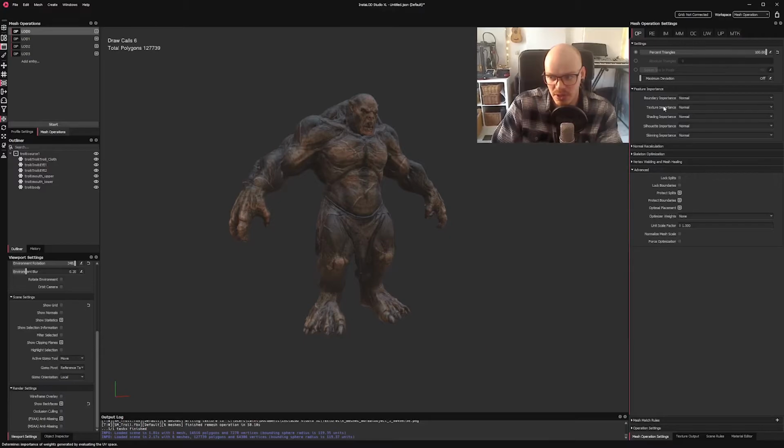That is only really the case when you've got really bad scan data. Most of the time, increasing the texture importance is more than enough. Maybe you're working with some automotive models and you need to make sure that the shading looks fantastic. Again, typically InstaLOD does generate some incredible results, even with 90% reductions. But if you do end up with maybe a broken normal somewhere that you're not happy with, no one's ever going to be happy with a broken normal, then you can start increasing the shading importance.